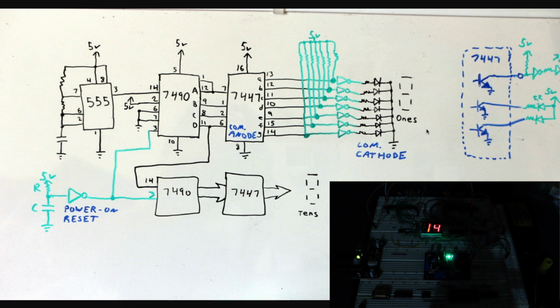the display. And if we want to have 2 digits, we cascade another counter, clocking it from the highest bit on the original counter. So the first counter goes from 0 to 9 and back to 0 over and over, and every time it rolls from 9 back to 0, the next counter will increment.